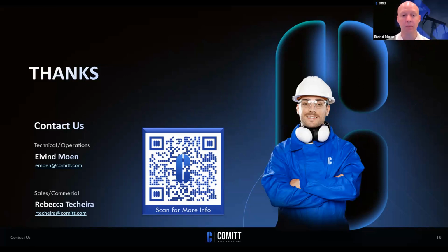I can. So starting on the proppant side, as I showed with our gauges too, our approach is that initially we'll break down everything with acid. With that, we map out the well and we find out where we have cross communication and where we don't, and then we can go in and do selected proppant treatment. So that's been our approach to mitigate some of the risks associated.